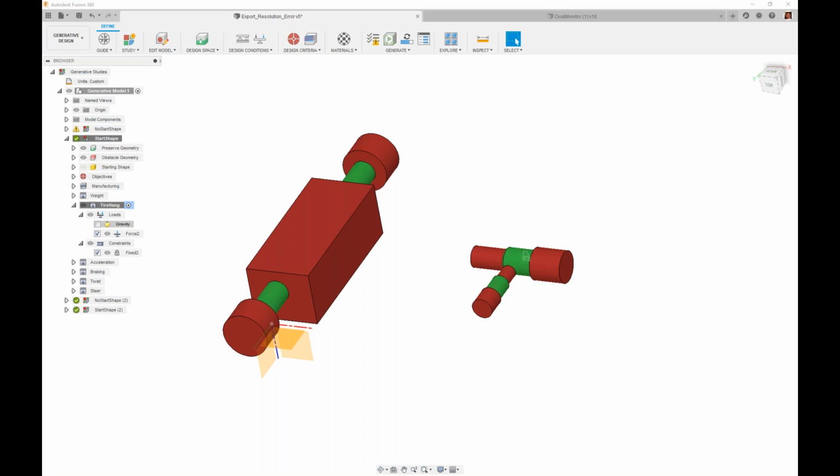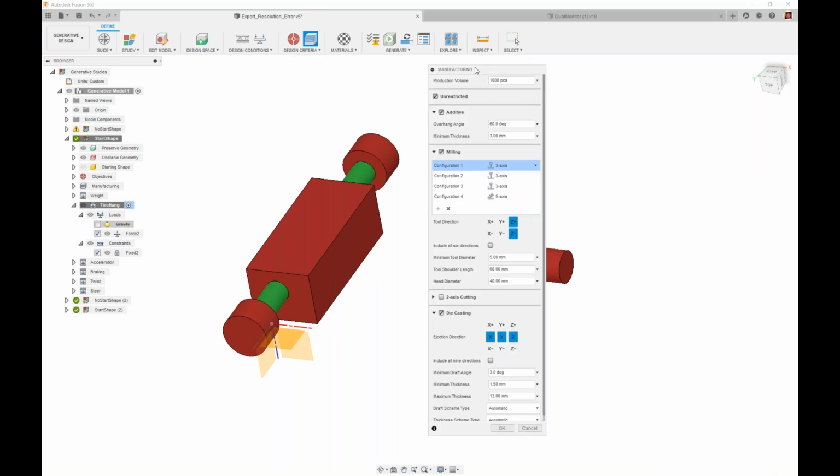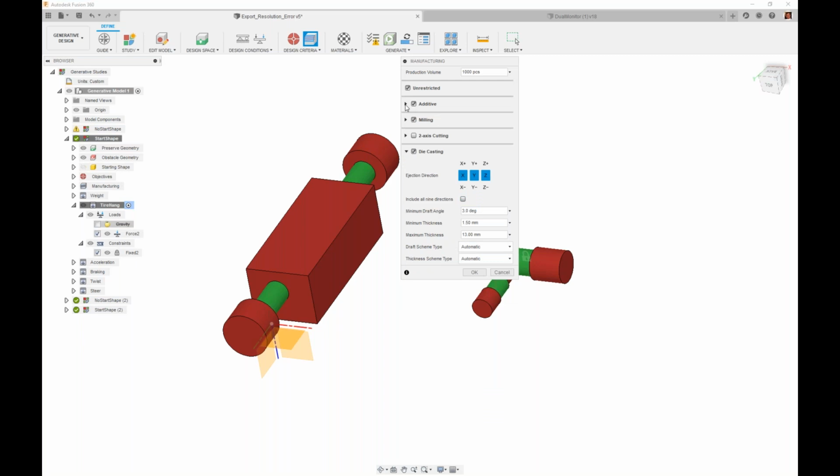As far as the inputs to the program, it's really going to be more on what that part experiences post-manufacturing. Like how is it held? What are the loads on it? Obviously, the material is an input. So from that point, generative design will help in terms of what it might look like. But you'd then certainly have to evaluate whether it's manufacturable via extrusion.